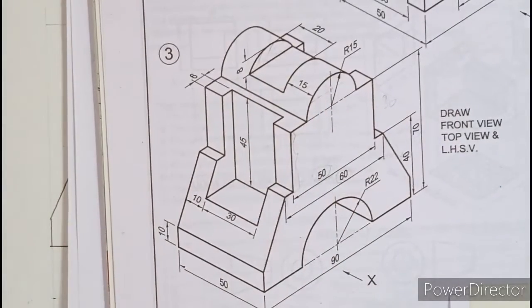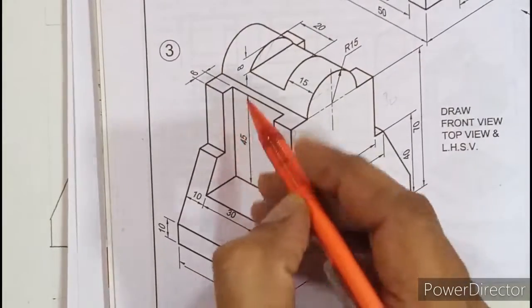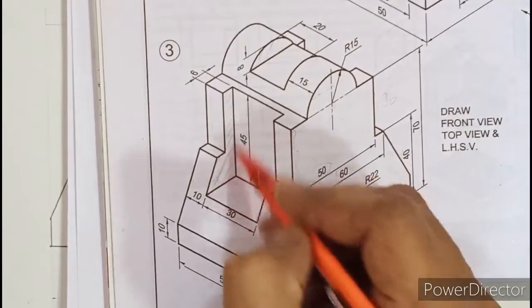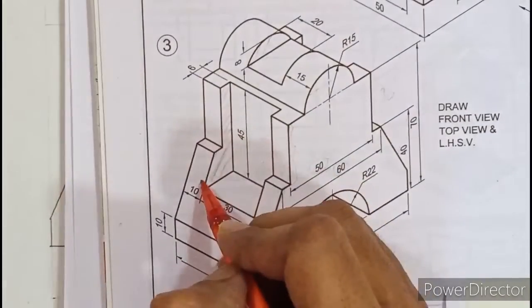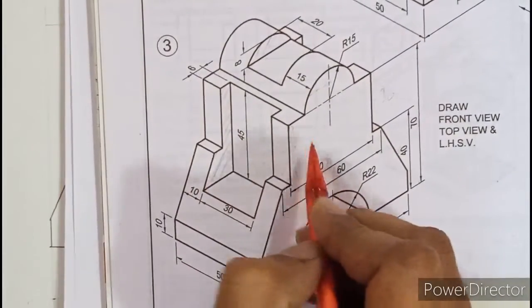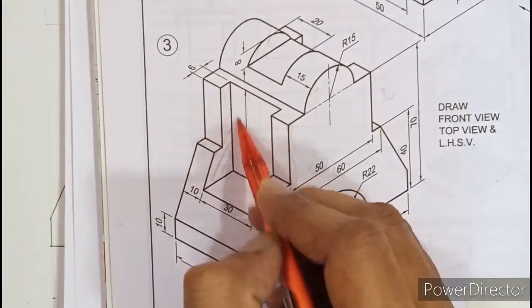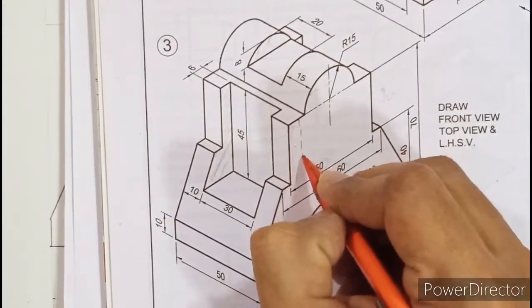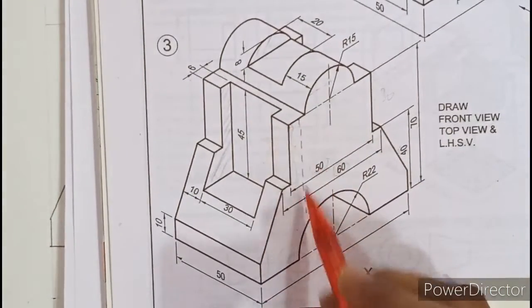Apart from this, can you recognize two more hidden lines? Yes, you can see that there is an L-shaped cutout. See this? There is an L-shaped cutout over here. Can you see that? This L-shaped cutout cannot be seen from the front. And if you look at the depth of it, it is 6 millimeter deep, and 45 mm you have to go down. So if you mark 6 from here and come down by 45, you can draw a hidden line like this, right? So this hidden line is 6 mm inside and 45 mm it comes down.